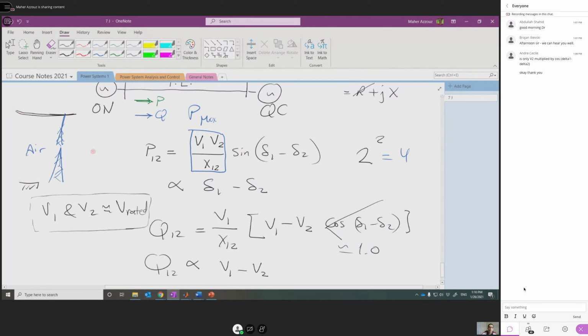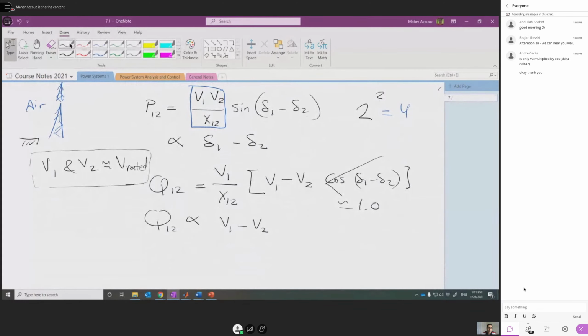So doubling the voltage means we have to increase the height by double, which of course adds to the cost of the transmission line, the cost of insulators, but we save costs in terms of the land requirements, or building a double circuit to serve the same load. Okay, so this is a quick summary of what we have discussed in the previous lecture.